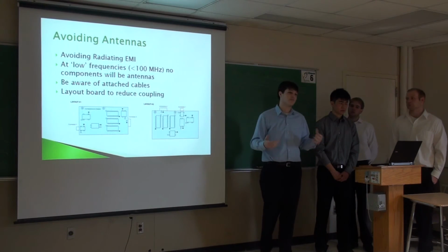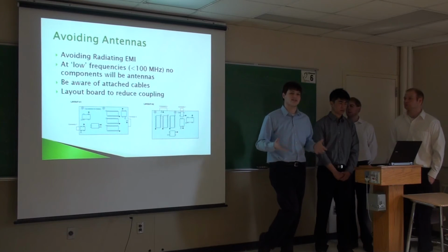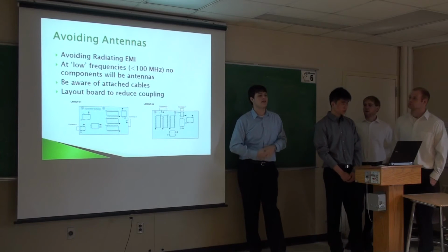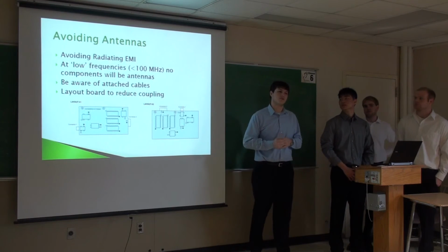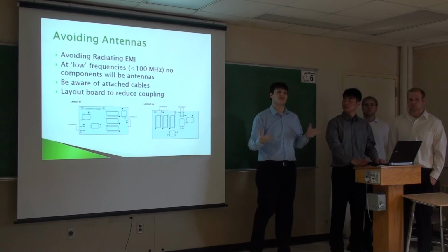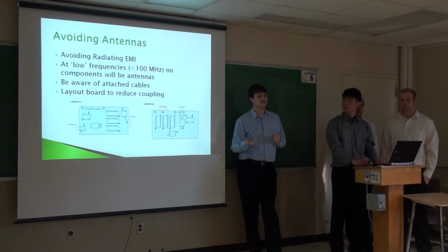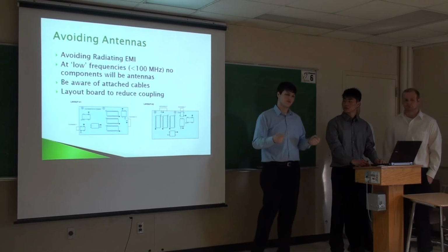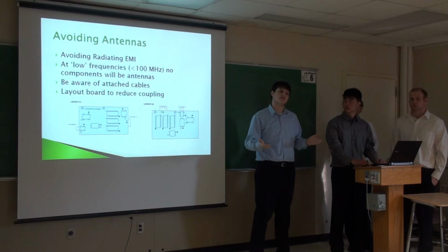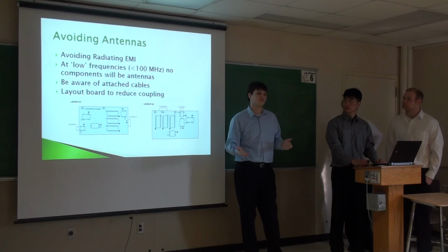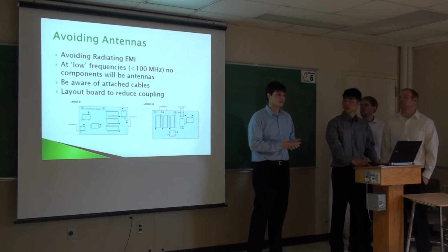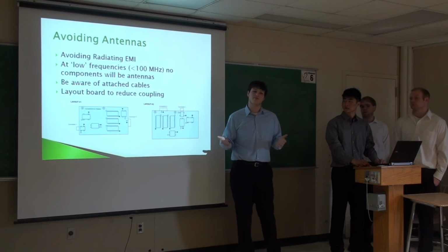Cables are much longer, and they'll meet that requirement fairly easily, and they can act as antennas. So if you have a layout such as layout 1 over there on the left-hand side, where the cables are connected on either side of the board, any noise they pick up will, if they're good cables, be picked up on both wires, so you won't get a lot of noise in the signal per se. But you've grounded those wires when they get to the board. So if they pick up different amounts of noise, you'll have different voltages on either side of your board. So now you've induced a voltage across your board, and you have current flowing all the way through your ground plane, which means you've induced a lot of noise across the entirety of your board by your layout.